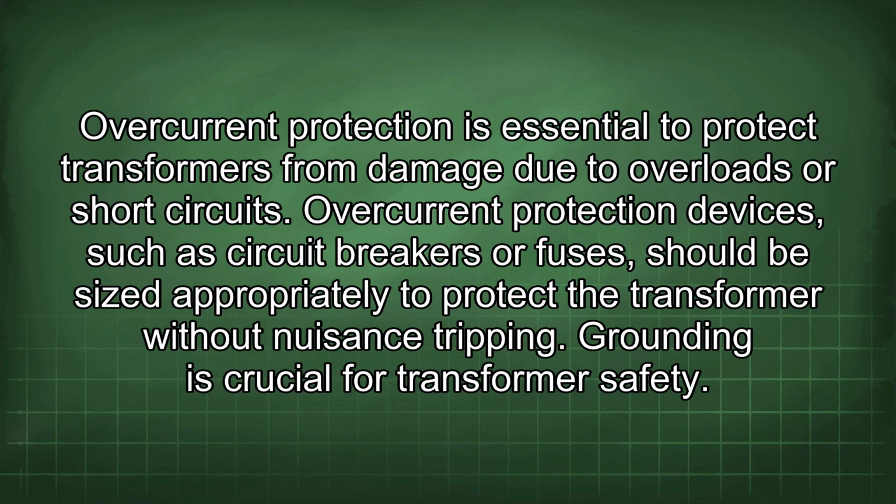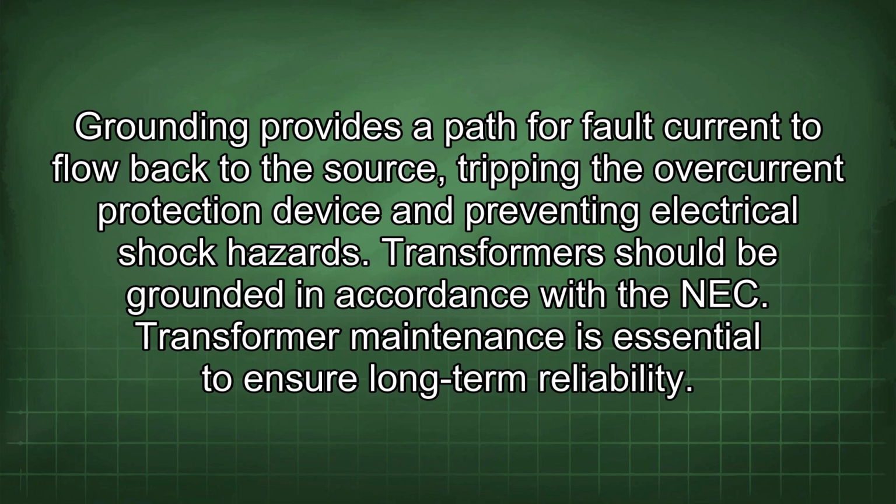Grounding is crucial for transformer safety. Grounding provides a path for fault current to flow back to the source, tripping the overcurrent protection device and preventing electrical shock hazards. Transformers should be grounded in accordance with the NEC.